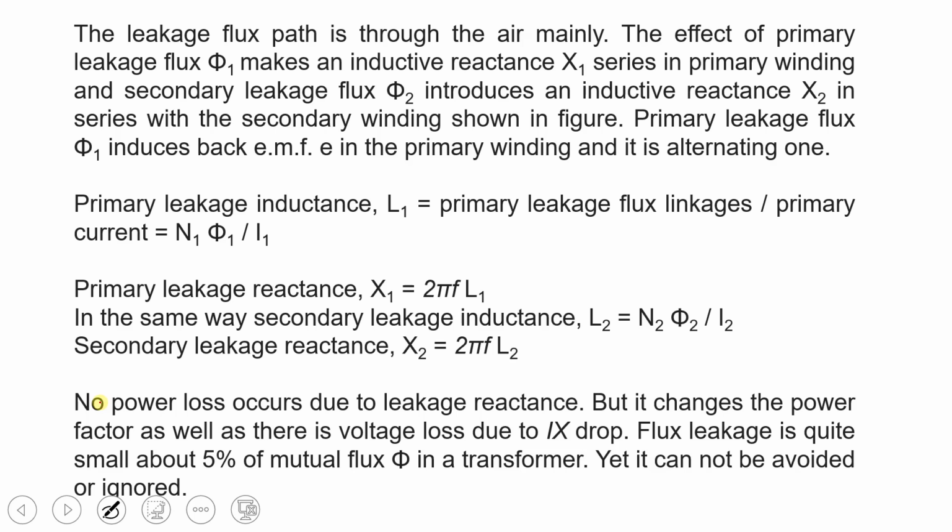No power loss occurs due to the leakage reactance. There is no power loss because of leakage reactance, but it changes the power factor. Power factor means cos phi. It changes the cos phi.